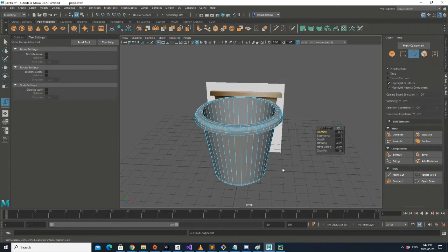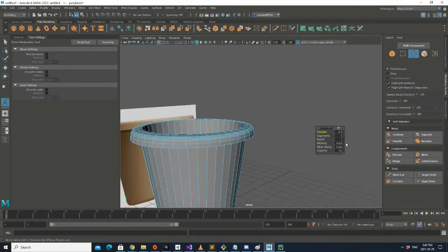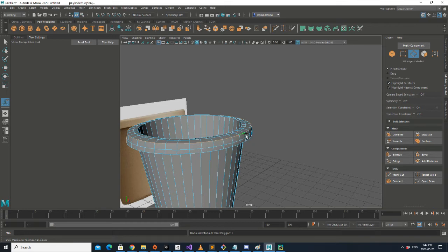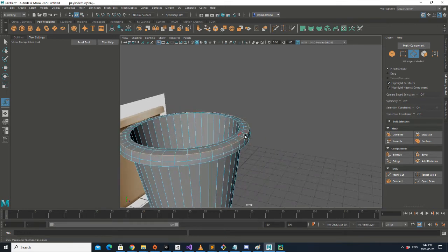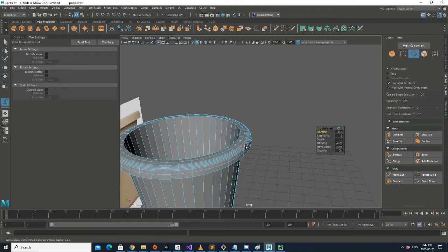If you just click on the bevel, you will see that it makes it smoother, and these are the parameters that it is working on. The fraction is the percentage, let's say what portion of this face is going to get smoother. So let me just go back. You will see that 50% of that face got smoother.